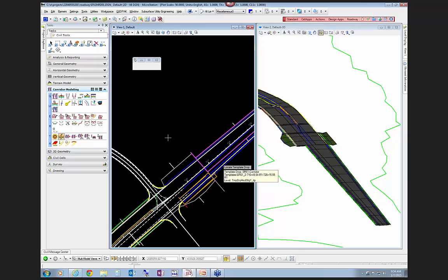Let's see, how would you create a template that you could use for A-cell, D-cell auxiliary lanes with a different cross slope at a ramp terminal without creating a separate template without the auxiliary lane? Again, I think I talked about this last week, where you can add in a pavement segment that's sloped at whatever that cross slope is, and then zero it out and have it look for a particular target or horizontal feature and only widen when it finds that feature. So that's how you would probably handle that.